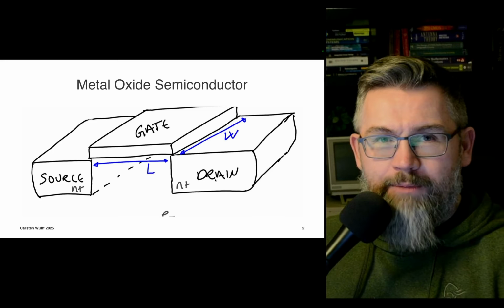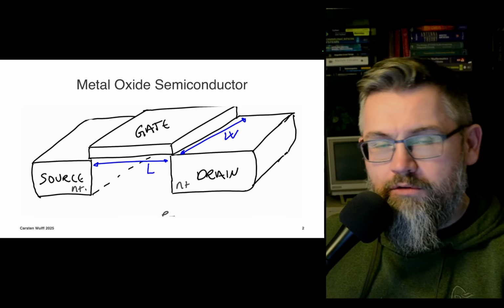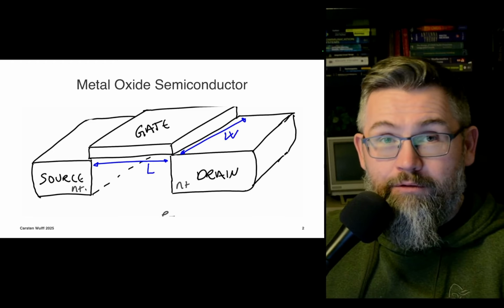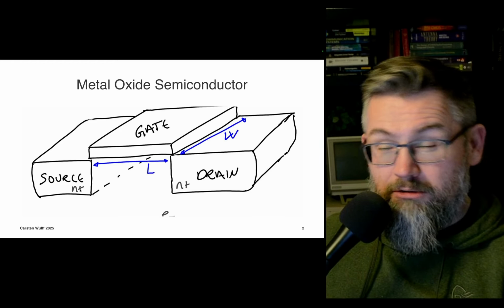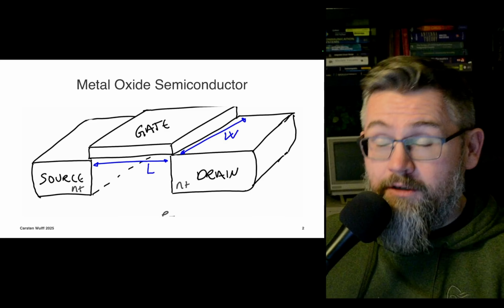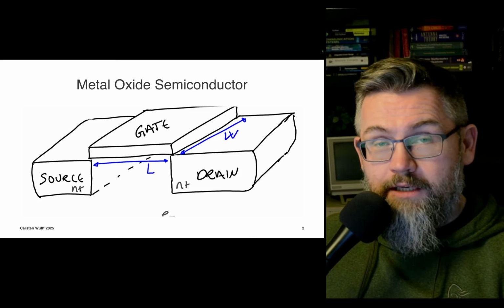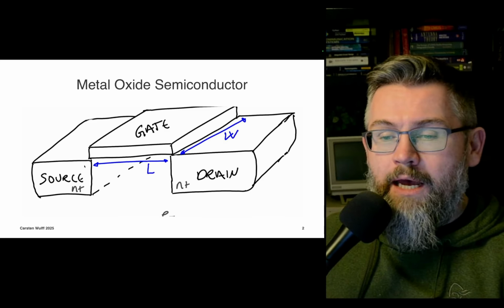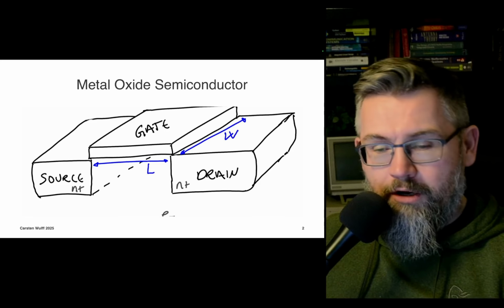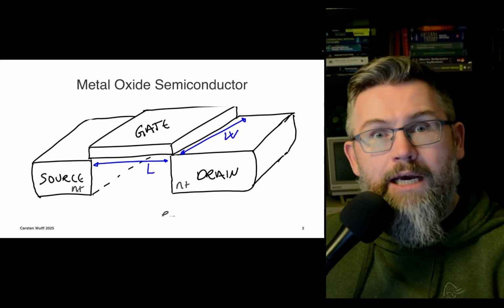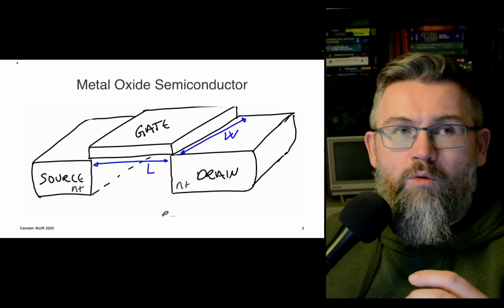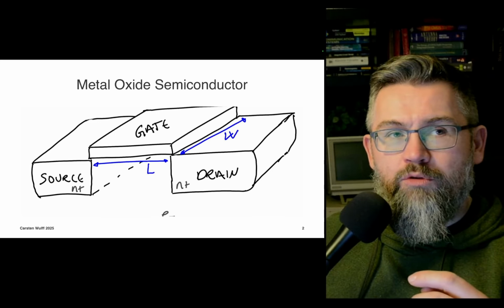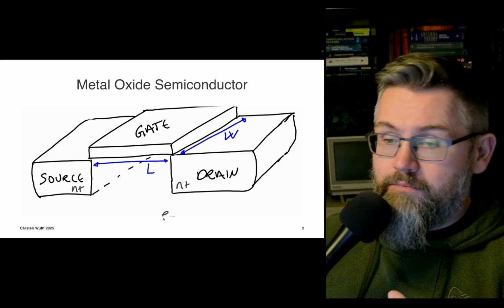And it's a three-dimensional structure. So the drain and the source, those are built into the wafer, implanted with, in this case, donors, for example, phosphor. So you implant phosphor into the silicon surface, and you create regions of higher doping, of more electrons, basically. The substrate is usually P- or some sort of P, so doped with boron. So that has an excess of holes.